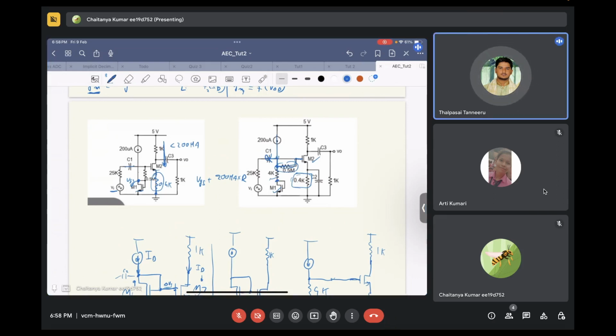So this circuit tries to implement degeneration in DC biasing so that this transistor becomes immune to VT variation, and then in order to compensate the voltage drop that occurs due to degeneration, it adds another resistor on the M1 side so that the loss can be compensated. Do you understand this completely? Yes, sir. Fully.